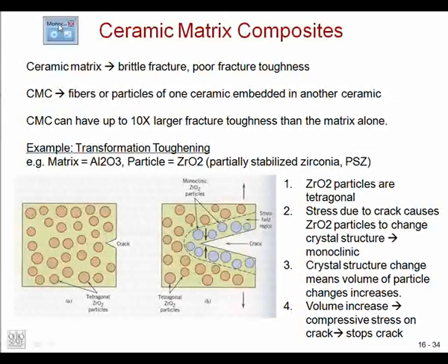And what happens is that stress is like an energy. You think of the crack tip, where there's this stress concentration. Normally that's going to lead to fracture. When we talk about fibers being able to bridge, or a compressive force at the surface wanting to close that crack, basically in the presence of that stress, the reinforcing particles will transform.